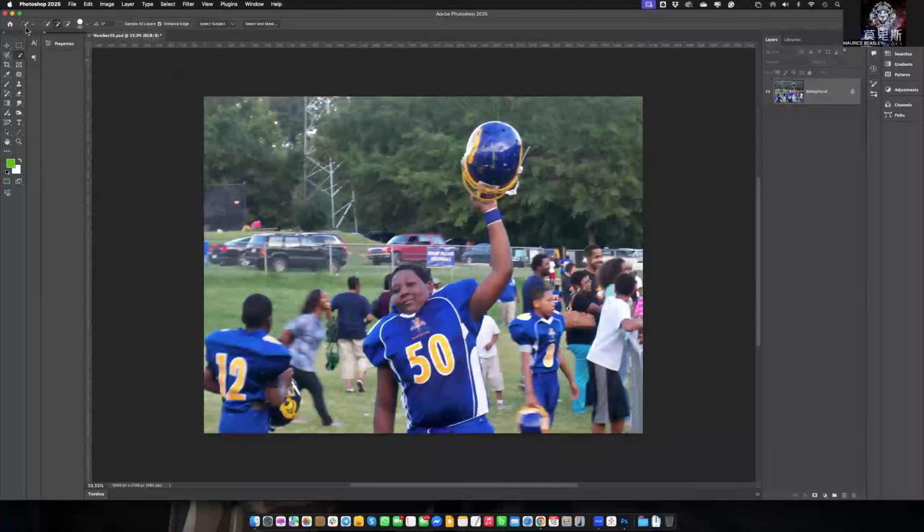Now, before you actually use the tool, a couple other things I would suggest you do up here in the options bar with quick select. Number one, the brush itself that you're using when you hit the little drop down to pick the brush. Mentioned this before, turning the hardness level down some, not a whole lot, just down within probably the 70s or 80s or something like that. So that way you have a slightly soft edge brush that you're using the quick select with. So this way, those soft transitional areas, like in the helmet, could possibly the face mask could be selected from the background, possibly. It's never going to be perfect, but it's going to be something to help with that.